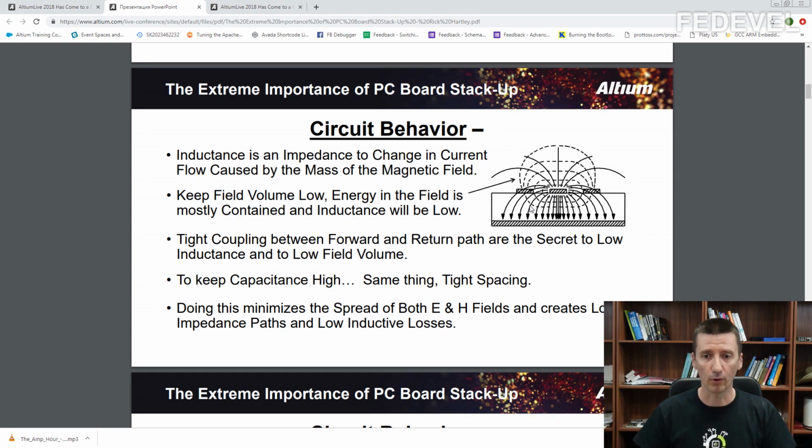It is going to influence also the other tracks on your PCB. All these other tracks are going to have their own fields too. All the fields will interact with each other. And that's not everything. When we have these fields very, very large, what does it mean? It means all our board may create all these kinds of fields which can be problems during EMC and EMI testing.